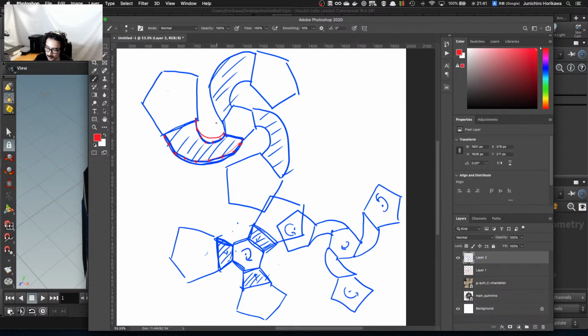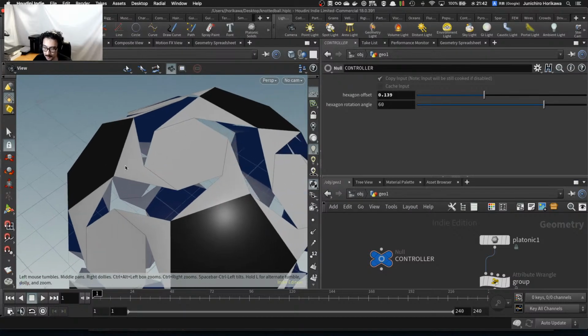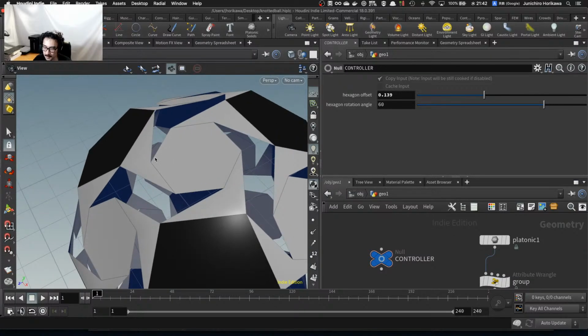So in order to do that, you need to have those points, but I could make that from the lines actually, using a resample node later on. So what I want to do here is to just create 2 lines which connect the edge, for this one, this edge, and this edge. And actually I don't really need the mesh in between for now.